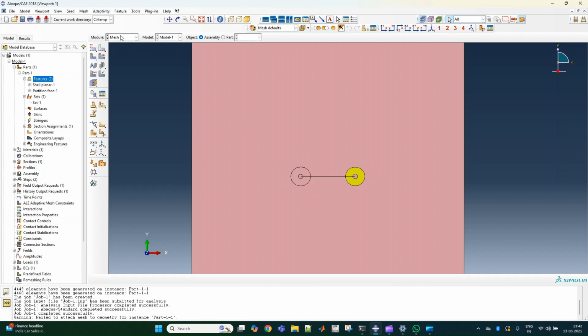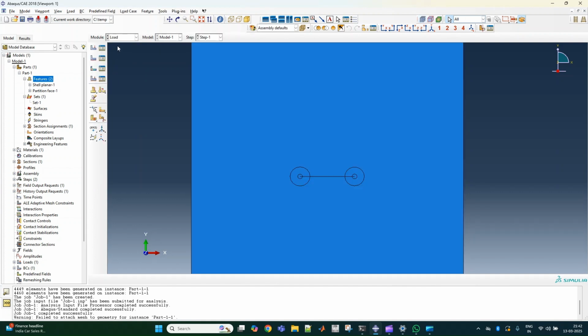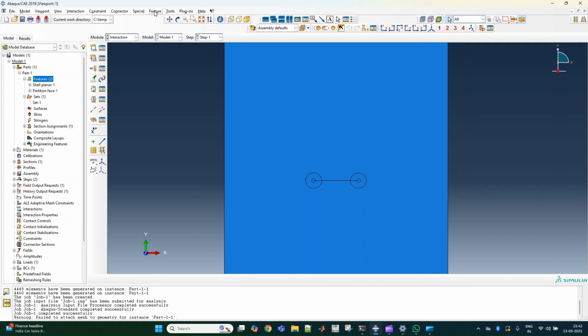One thing we forgot: now that it is an internal crack, it is different from the edge crack. The crack has to be defined for both ends as two separate cracks, even though it is a single crack. From the mathematics point of view, the software treats it as two things, because the contour integral works for only one circle.